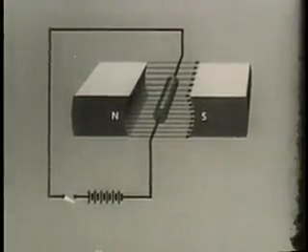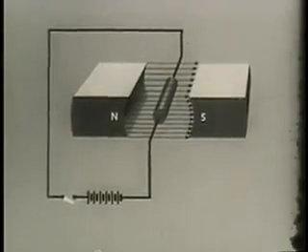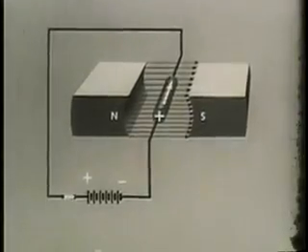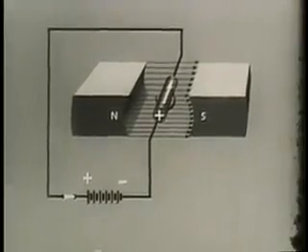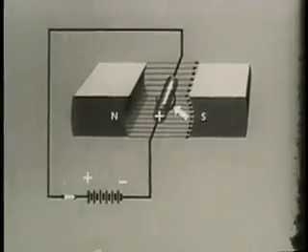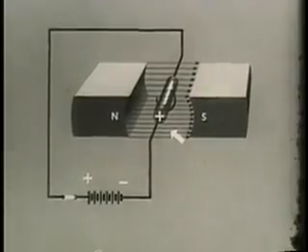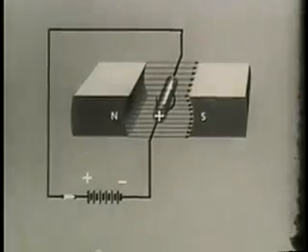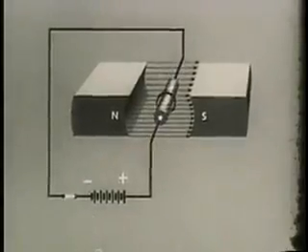To see what really happens, let's go to a drawing again. Here, a conductor is suspended in a magnetic field. Current flow from a power source creates its own magnetic field in and around the conductor. This field around the conductor reacts with a main magnetic field to cause motion of the conductor either out of the field or into it. The arrow point indicates the direction of the current flow in the conductor.